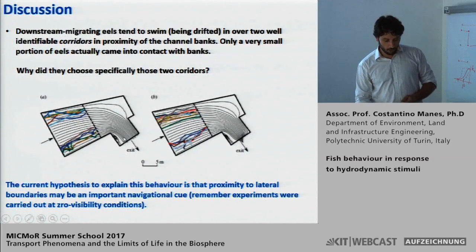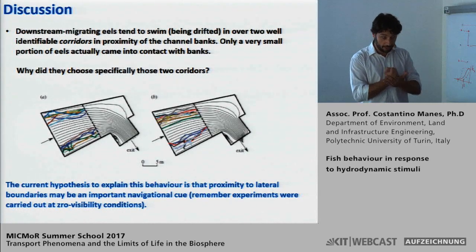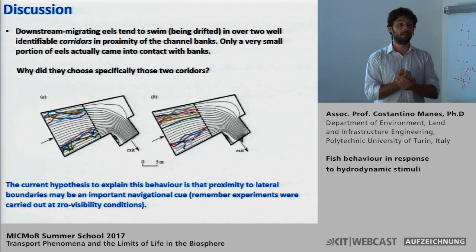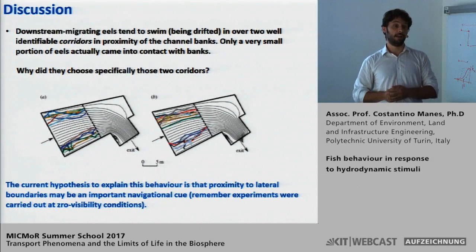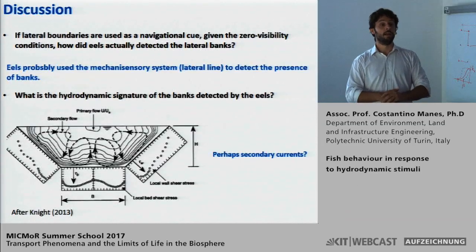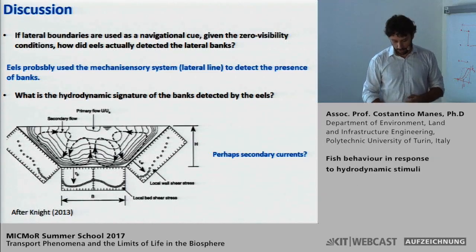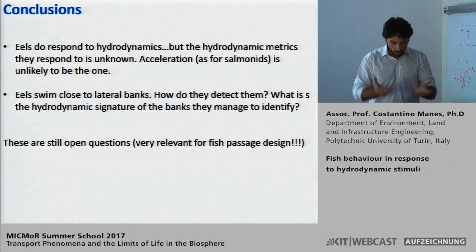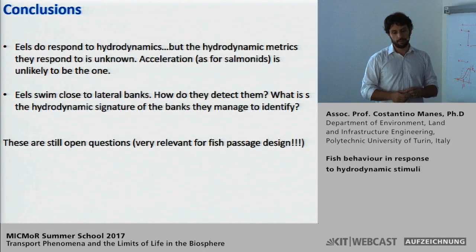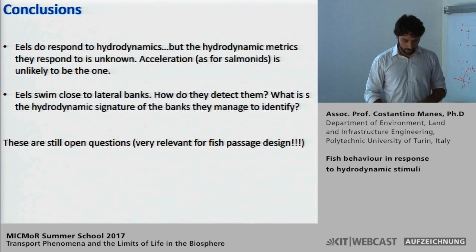And if I understand what really repelled eels in the barrier, so I really know what is the metrics that generated these rejections, then I can find hydrodynamic ways to implement them in proximity of dams, and therefore prevent eels from going to screens or being trimmed into the turbines. So I think this whole study really integrates fundamental science with clear engineering applications, so to me it's really, really interesting.